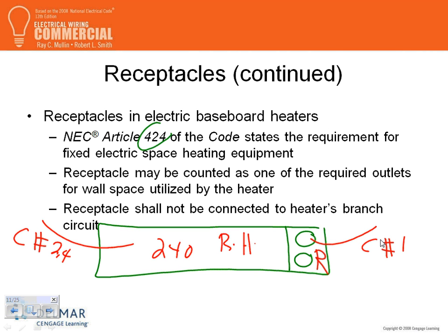No change in residential. Now, Brooks, my friend, do the rules of 6/12 for receptacle layout apply for a commercial building? The answer is always no. So the 6/12 rules of laying out receptacles in a commercial building, or anything other than residential, do not apply.